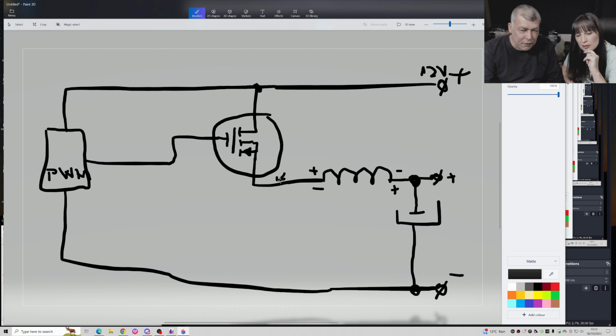So how are we connecting this to ground? Because if I just use a wire, then the MOSFET is shorting plus and minus. You can't use a resistor on a circuit like this. You use a resistor when you want to reduce the current. So how can we connect this to ground without shorting? I want to connect the ground only when the coil is bouncing, not when the MOSFET is on, because if it's on and this is connected to ground, it will short the plus and minus.